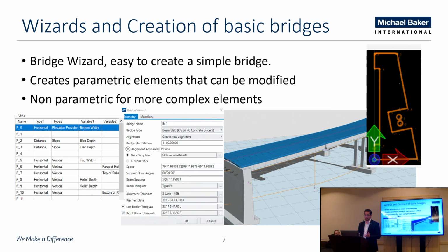You've really got that solid understanding of where that bridge is. It's located, geo-referenced, absolutely correct, vertically, horizontally, and then you're bringing in all those templates that I mentioned as well. So you've got, say, a UDOT barrier or a TxDOT barrier. All that information is there, correct. You've used those templates, but it's not perfect.